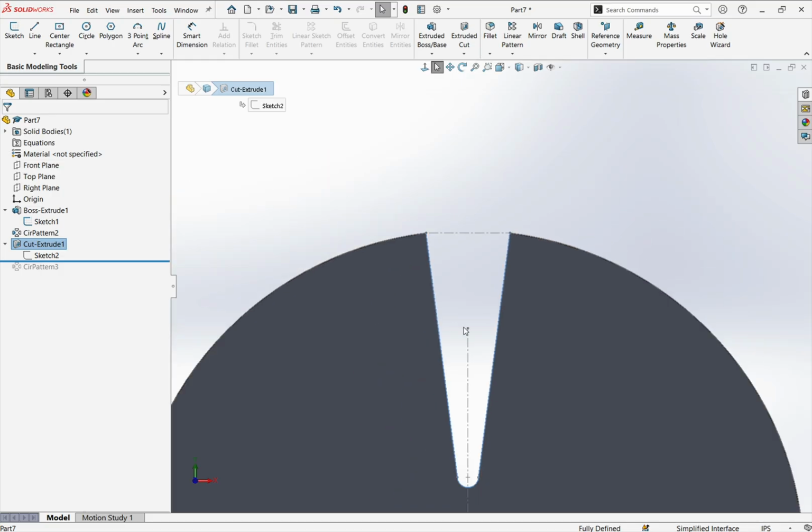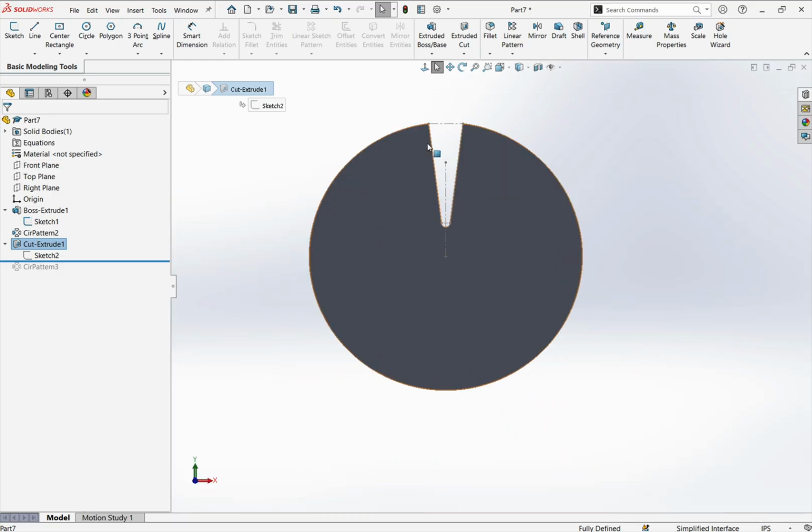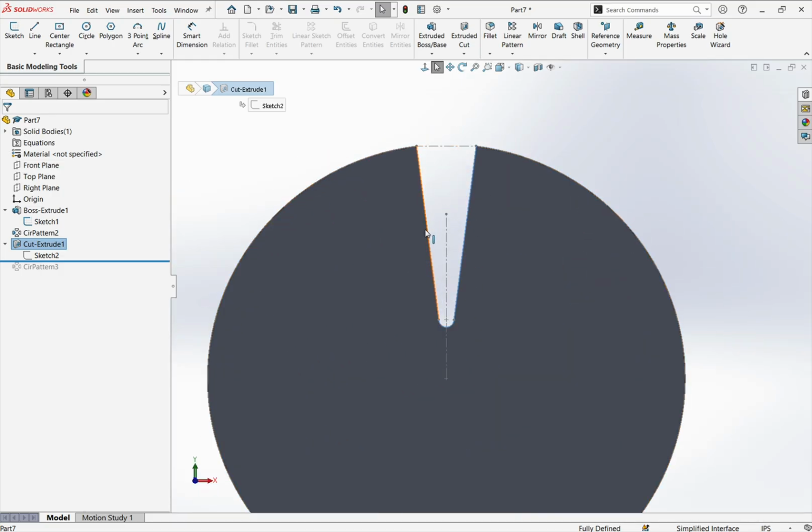So now I got basically my cutout feature, if you will, back after I did this. I could have just deleted the circular pattern, right? If that doesn't make sense, you can try this. You can follow these exact steps and then convince yourself that I could have just deleted the circular pattern and I had this shape, okay? However, the problem would still exist. I don't have a feature to pattern. I needed to cut. So that's why I did this second sketch and then did this cut.